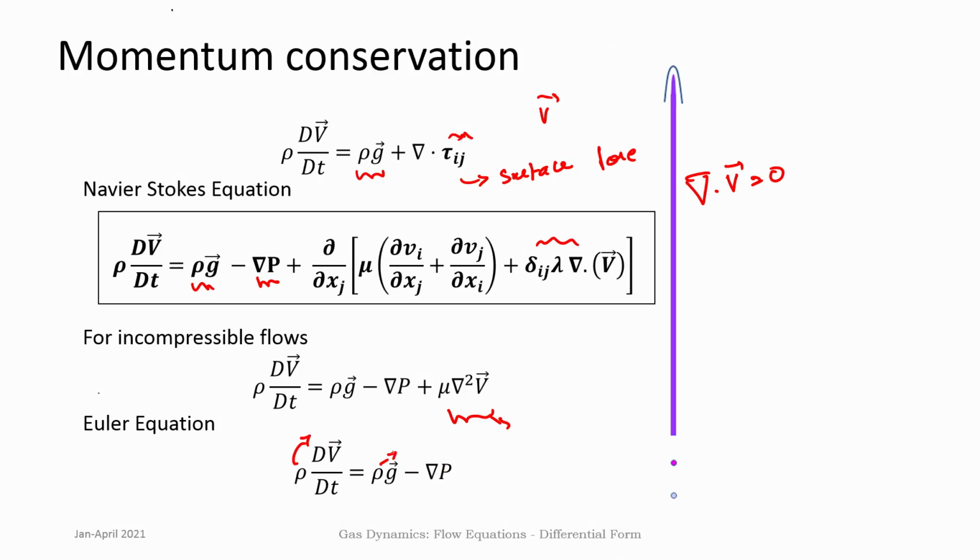So, this is Euler equation, where rho is a variable. This is an incompressible flow equation where rho is taken as a constant. So, these are various forms of the momentum conservation equation. The most general form is represented here and expanded over in this equation.